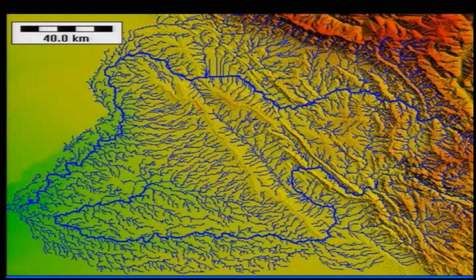So, this portion becomes your drainage divide, whereas this portion is not occupied much by the drainage, and this is your flat area. So, one can also take into account the drainage pattern and try to identify what type of structure is sitting in the subsurface. So, this clearly marks that this portion is a folded area. If you take the cross section here, you will find that it is something like this. Okay. So, you have a slope in this direction, and a slope in this direction.